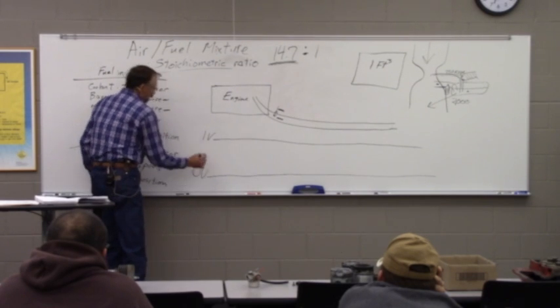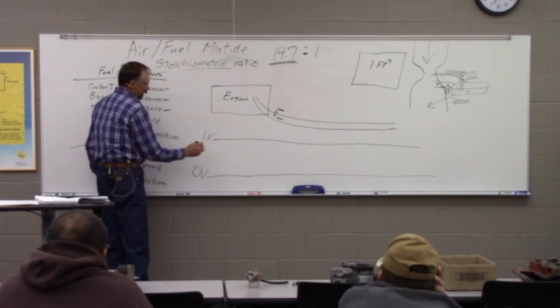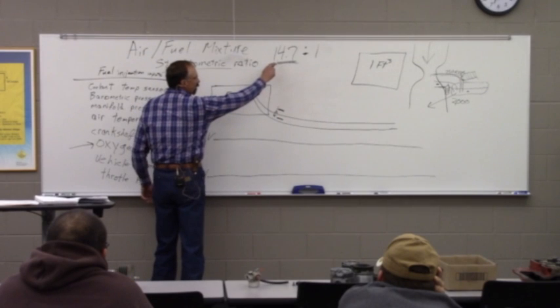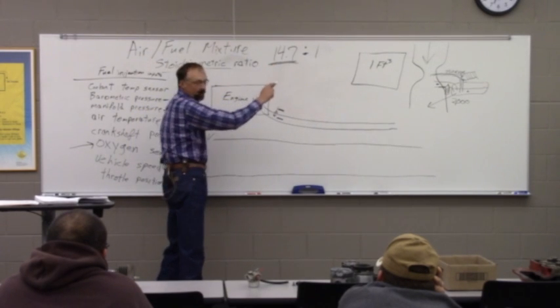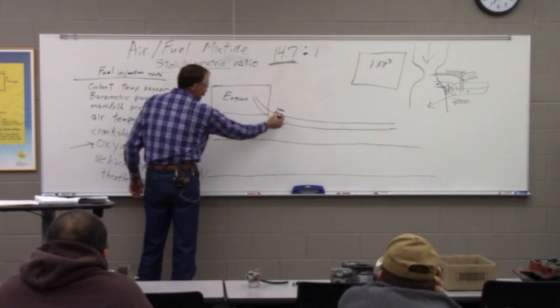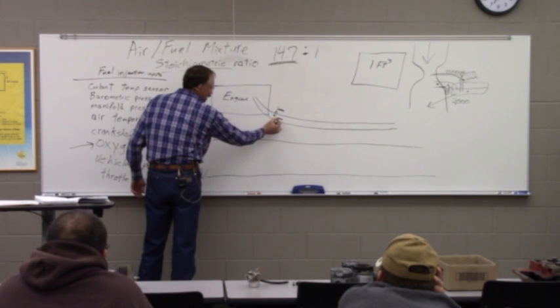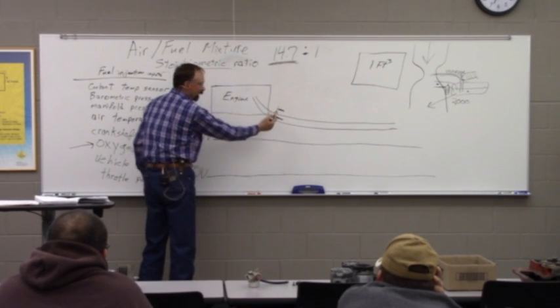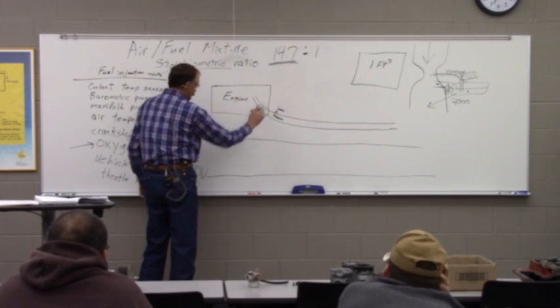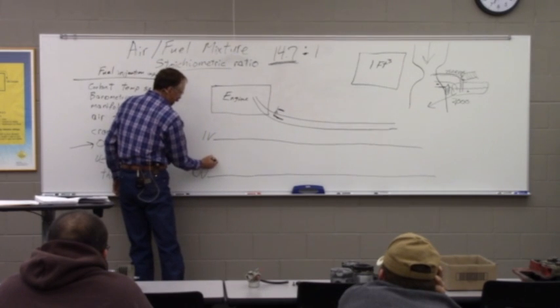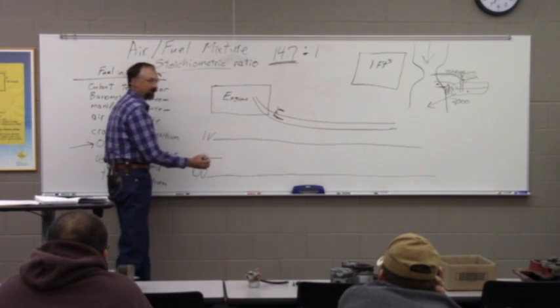And if we're hitting this ratio of air to fuel just exactly right, the difference between the little bit of oxygen left still in the exhaust after it comes out of the engine and what's out here in atmospheric air will be at the level where that sensor produces just barely under half a volt.